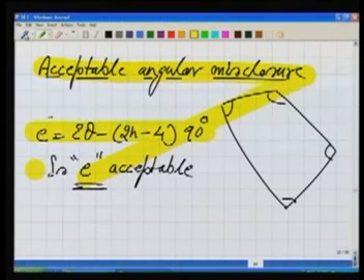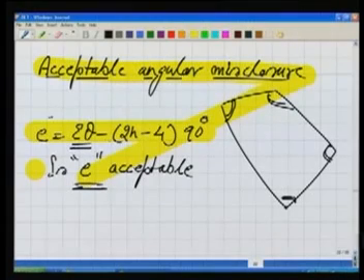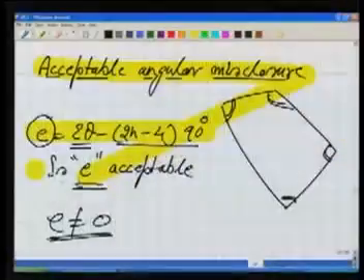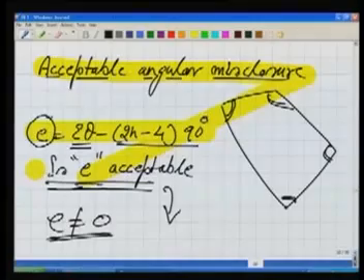We say that if you are doing a traverse, we are measuring these angles, and if you find the sum of these angles minus (2n minus 4) into 90, which is 360 in this case, we find this particular value E. If this value E is 0, there is no angular misclosure. But if E is not 0, it is a finite value. Well, is that value of E acceptable? How do we determine whether it is acceptable or not?